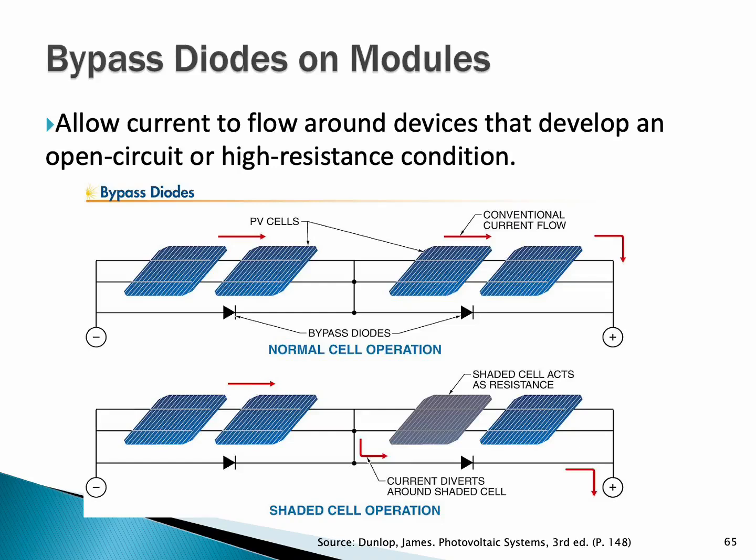So these bypass diodes are things that can malfunction from time to time. Now we have to take that module out of service and replace that module. And how often does that happen? I don't know. I've only seen it once or twice. It's not common to me, but on big systems, this may be a couple a year.